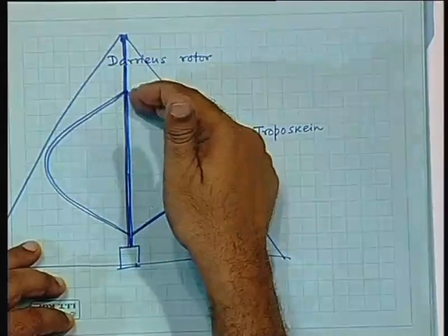So if you build into it a strength along the direction of the length of the blade, then obviously it becomes more stable. It's very difficult for such a blade to break, which is not true for horizontal axis wind turbines. There can be forces which can make those break, but here nothing will happen. So the structure is that you have the vertical axis and you have the blades that are shaped like this, and this cross section is the airfoil cross section. Clear?